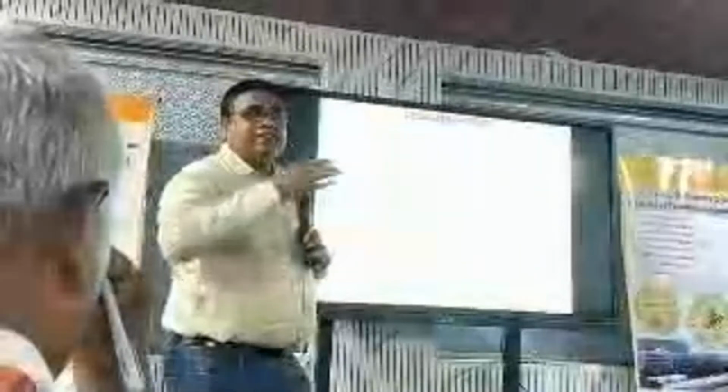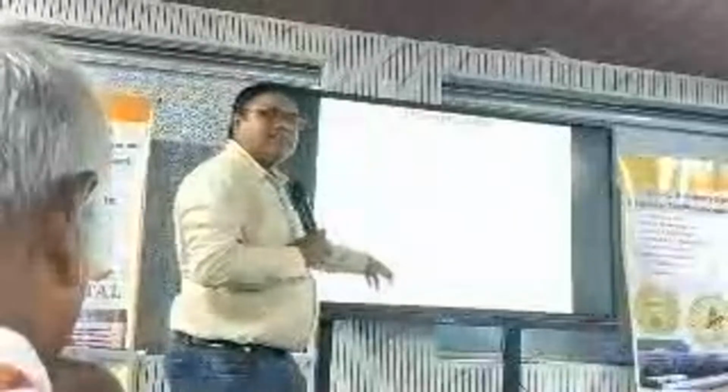First we have to collect the data, the machinery, RPM, frequency, everything we have to collect. And what is the disturbance frequency? What is the RPM divided by 60? That will give the disturbance frequency. And what is the total equipment mass? The mass which is coming to the first stage mounts. And that natural frequency we can calculate. If that frequency fD by fn is greater than root 2, why greater than root 2? We have seen the transmissibility curve. If it is greater than root 2, isolation zone. If it is less than root 2, it is amplification zone. So we have to create that equipment such that fD by fn is greater than root 2, then only it is valid.